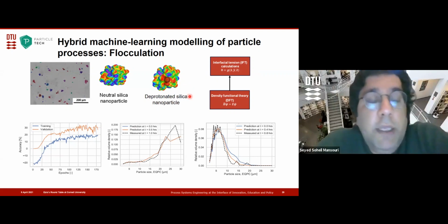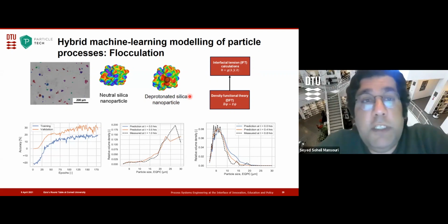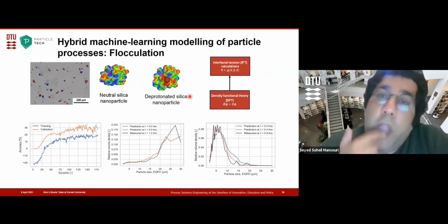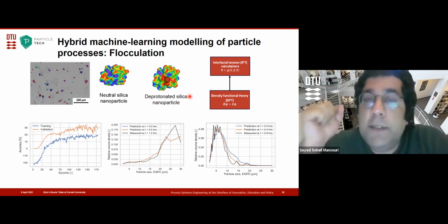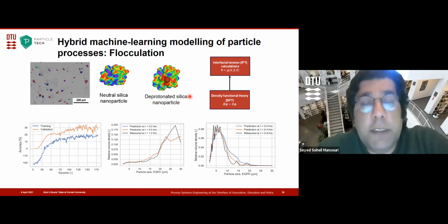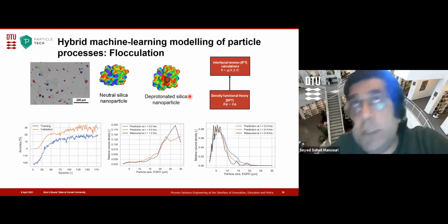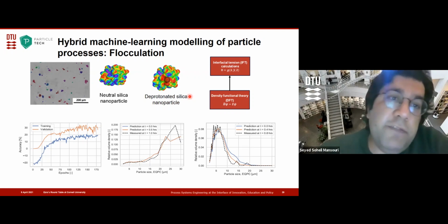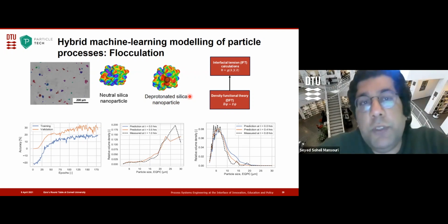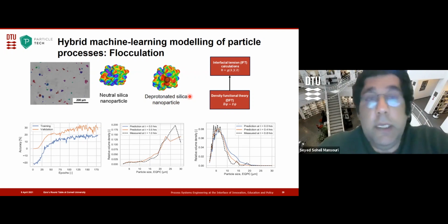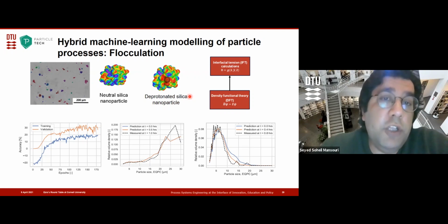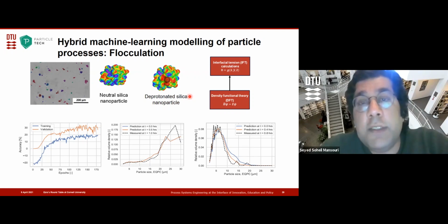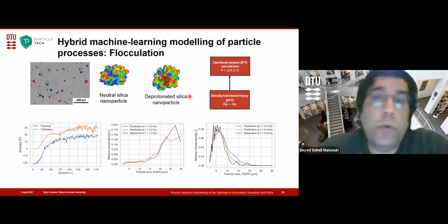However, quite surprisingly, there is no control or monitoring system available today for these processes in the industry. So often the control is like this. It is taste-based. Operators take a sample, measure the turbidity or just look at it, and then say if it is good or not. But what happens in reality in biomanufacturing is that a lot of expensive pharmaceuticals or bio-based specialty products are actually lost in the flocs because of the lack of control on their breakage or agglomeration.